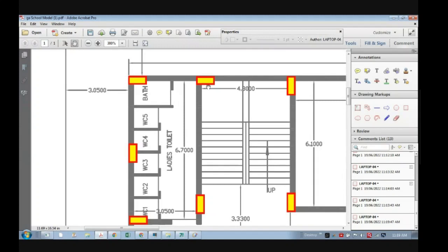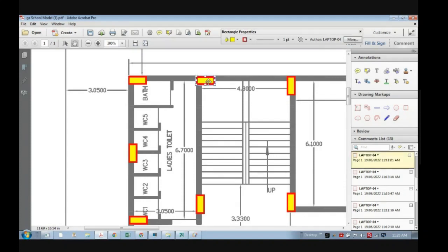Now, is there a better way, should something be different? It should be different. So what should be the orientation, should it be vertical here? Sir, horizontal, sir. Okay, the person who is saying horizontal, please justify, why do you feel so? Because our lengthwise wall is so long. Longer span towards horizontally, shorter span towards vertically. So if the spans are longer, then I think it should be provided towards the longer side.